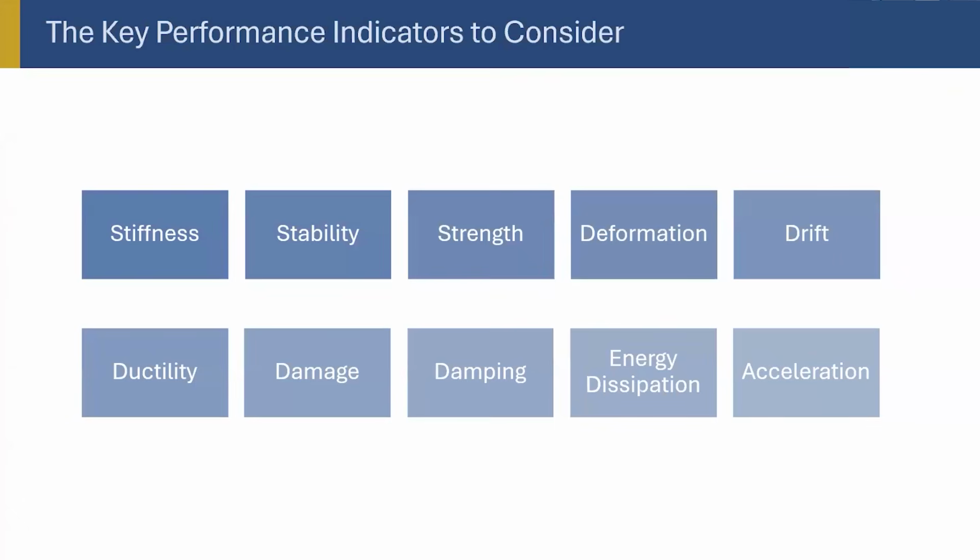Energy dissipation, another important thing we talked about, that when we are going to apply any hazard, energy is going to come into the structure, whatever it is. And that energy has to be either absorbed or dissipated. If you absorb the energy too much, when the structure fails, that energy will be released like an explosion. So you need to dissipate the energy as we go along. So energy dissipation is very critical. It's related to damping, it's related to damage, it's related to ductility.